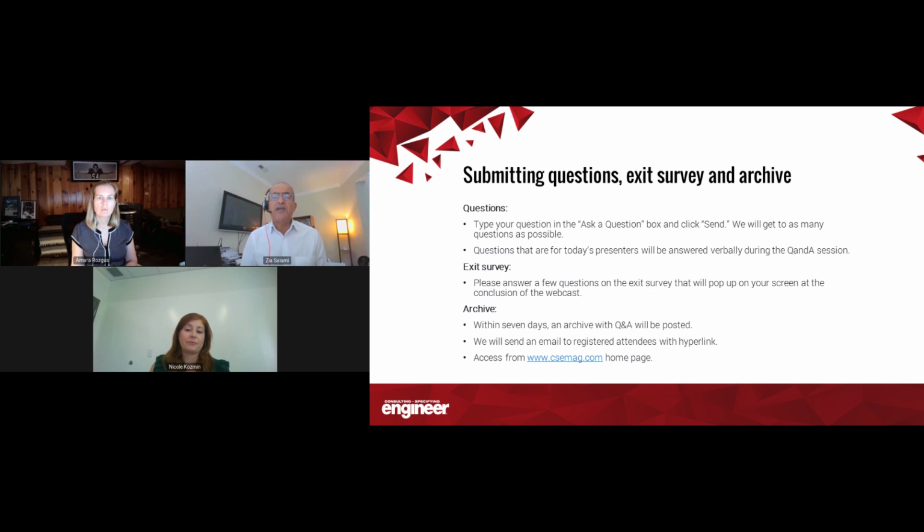The second, as I pointed out in the presentation, is that UPS will create harmonic distortion. Therefore, we sometimes ignore it, and we need to pay close attention. The third one, probably there are many, but the third one that I can think of is selection of the right battery for your application and the amount of runtime that you need. For example, if you need it for a safe shutdown, if you need it to back up your data center, if you need it for a different application, you need 10 minutes, 30 minutes, 1 hour.